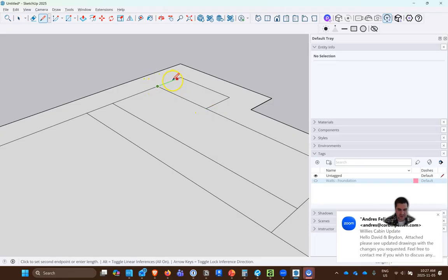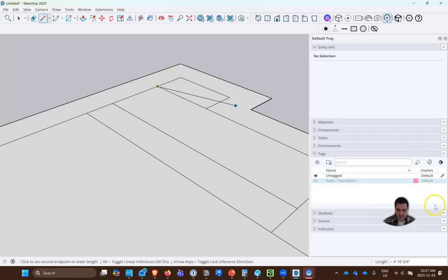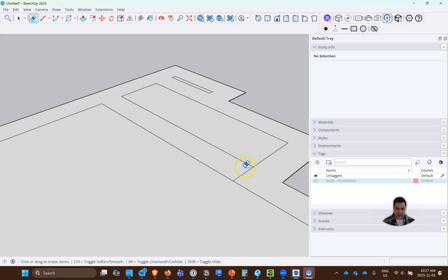Honestly, if I was doing this on site, I would probably not frame this in. I would probably just make that solid, just because having that little airspace, you'll never be able to get the formwork out of that. So I would just frame that solid. But for all intents and purposes, we can leave that. So that's what we're looking at here.